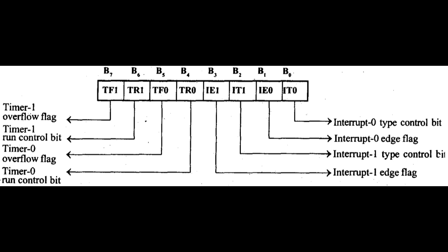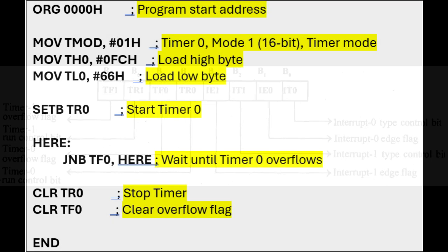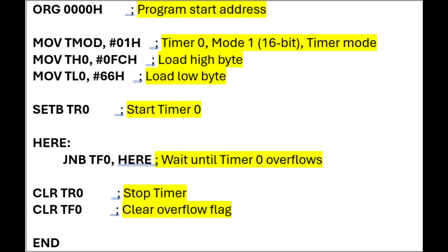How to start the timer? Using TR bits. TR0 equals 1 starts Timer 0. TR1 equals 1 starts Timer 1.